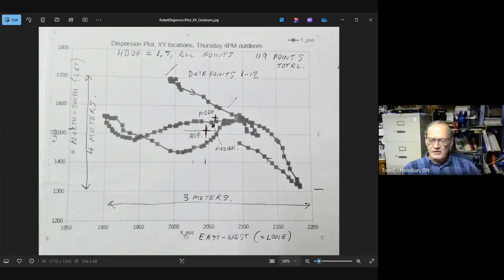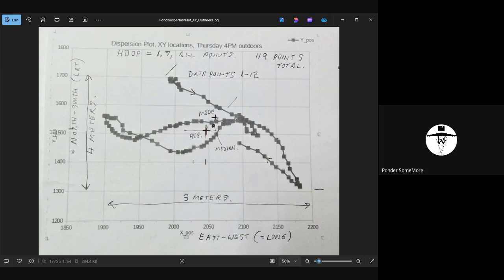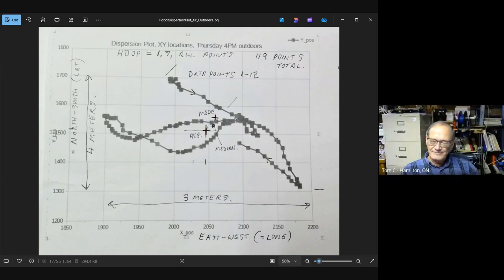Yes, and I was starting to look at that, and one of the questions I had was, is it sufficient to go differential GPS with only L1 signals, or do you need to go to L2? You've got to have both for RTK. That's what I was afraid of. Yeah, okay. Well, no, you can't.